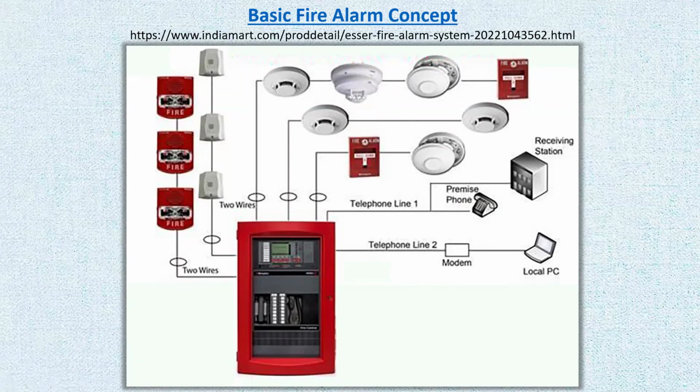Smoke is not supposed to be in the air supply ducts, so those detectors can detect it. Sometimes it makes more sense to install a heat detector than a smoke detector. For example, in the boiler room, when there's a fire, there's heat first and then smoke. Sometimes people do double protection. They would install heat detectors and smoke detectors.